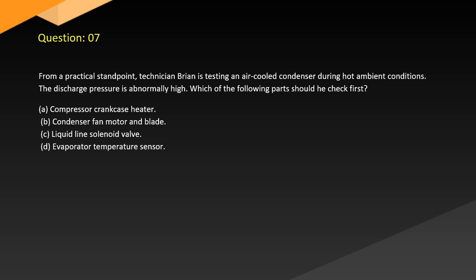Question 7. From a practical standpoint, technician Brian is testing an air-cooled condenser during hot ambient conditions. The discharge pressure is abnormally high. Which of the following parts should he check first? A. Compressor crankcase heater. B. Condenser fan motor and blade. C. Liquid line solenoid valve. D. Evaporator temperature sensor.